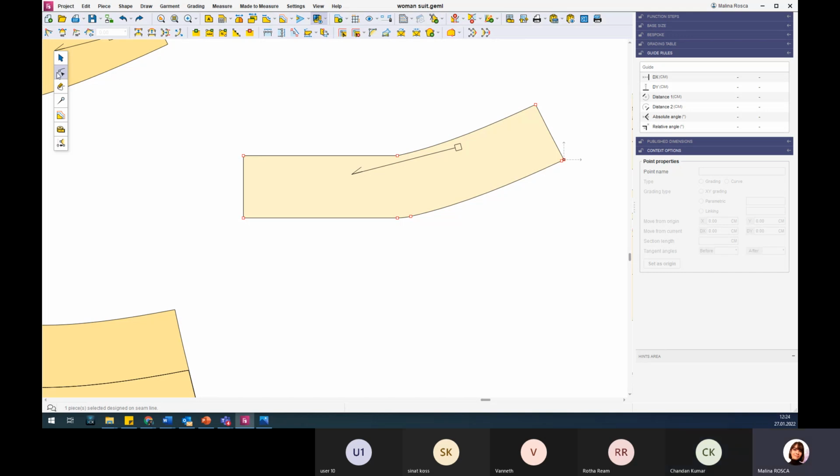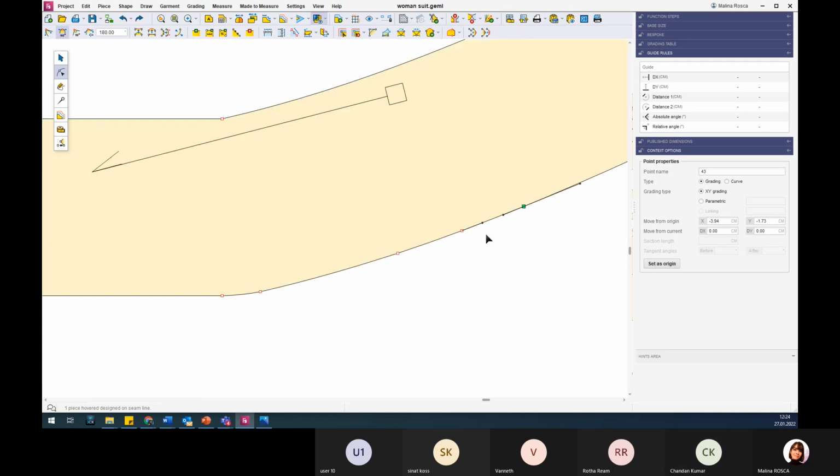No. If you are in the shape mode, you can just double click and delete, and also double click for creating. So we need to use the delete key from the keyboard? Not really. You can. So I'm going to create 3 points with double click. And I have the possibility to delete them by selecting and pressing delete on the keyboard, like this.